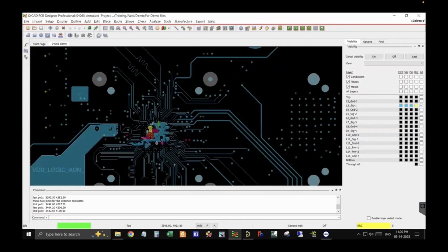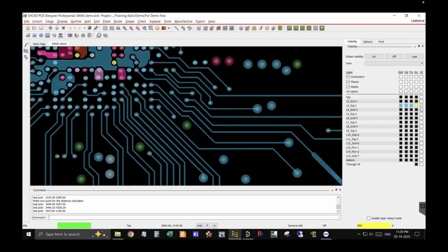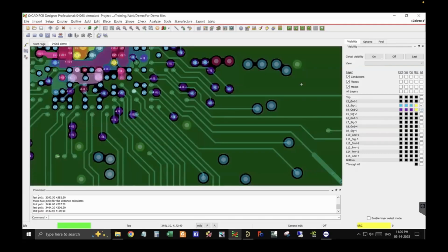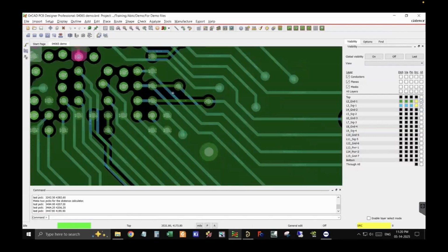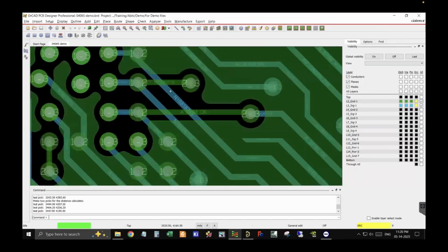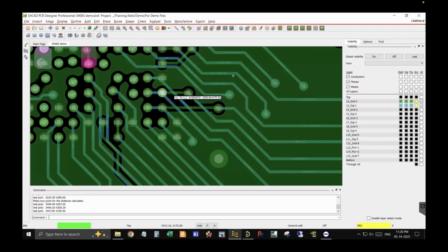Layer 3, the references were not proper, as you can see over here. So we wanted references on both sides. As you can see, the references are getting cut off over here due to the fan outs, because a lot of fan outs was going on layer 3 and layer 5, because all the signals that are going up to 9, 7 and 7, 9 and 11 also will go through 3 and 5.